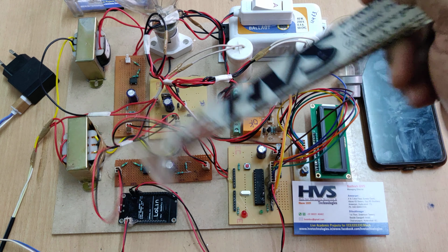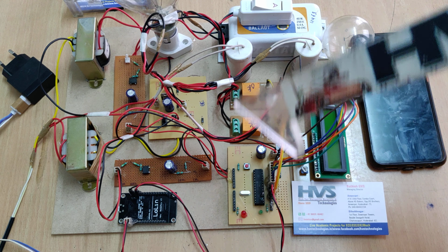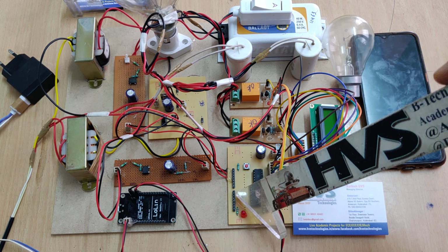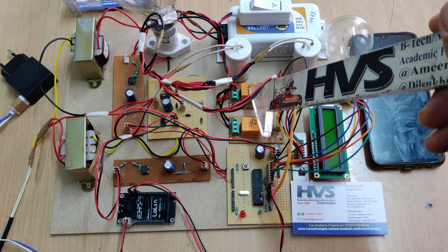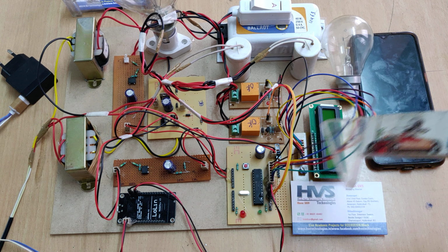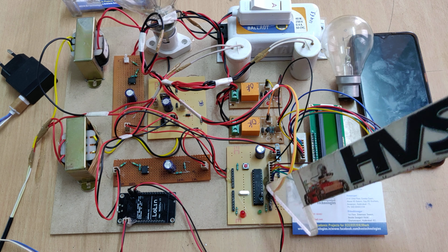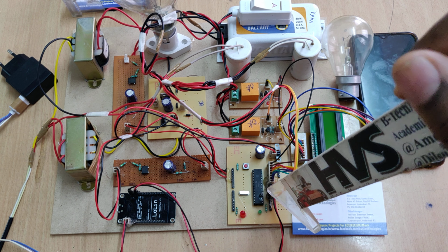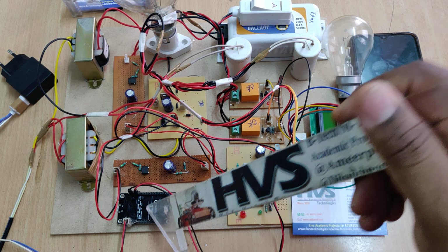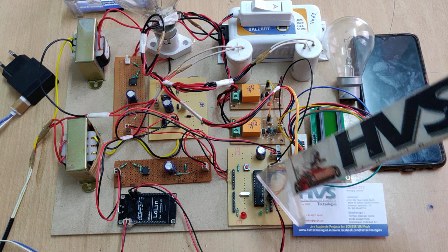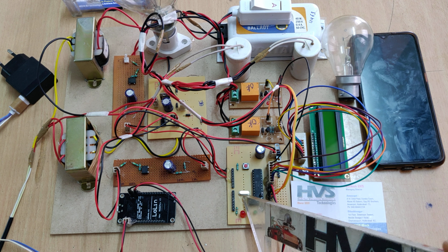And the flow is, current transformer, voltage transformer, and after that these two waveforms will be fed to the PIC microcontroller at A0 and A1 pins, and next the outputs are electromagnetic relays connected at C6 and C7, and the power factor value will be displayed on this 16x2 LCD. It is connected at B2 to B7 pins of the 16F73 microcontroller we are using, and parallelly it will send the power factor value through serial communication to the node MCU from the B0 and B1 pins. And here this is the reset switch, and this one is a crystal oscillator, so it will provide the 20 megahertz crystal oscillator frequency.